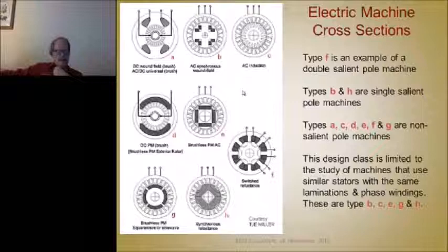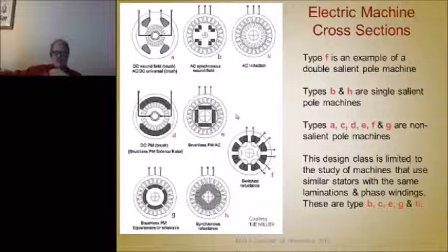That's better. In this case, the last thing I wanted to show you about this was of course the induction machine, which has the same stator as this guy, but it has a different kind of rotor in it. And we're going to talk about what that rotor consists of. That's a punch lamination with slots in it, and those slots are filled with current carrying conductors. There's a couple ways you could fill it. You can wind them, or you can cast them in there.